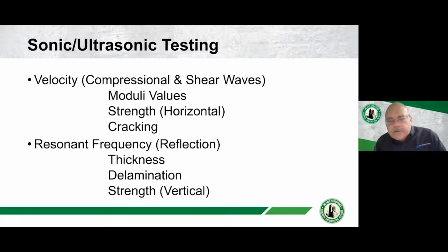I'm talking about Young's modulus, the bulk modulus of a material, or Poisson's ratio. So that information, based on velocity of basically sound waves, can be equated into the in situ compressive strength for concrete. That's the velocity testing.